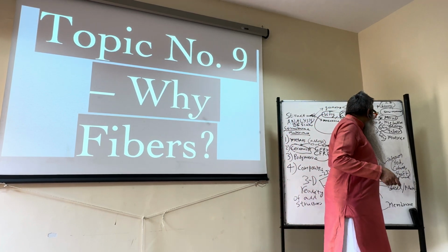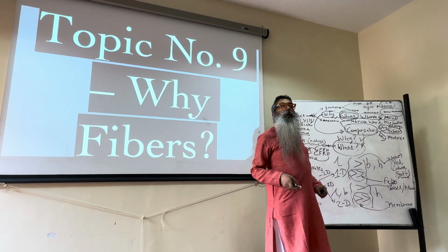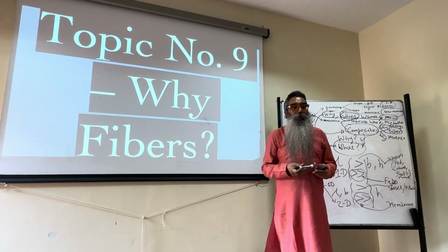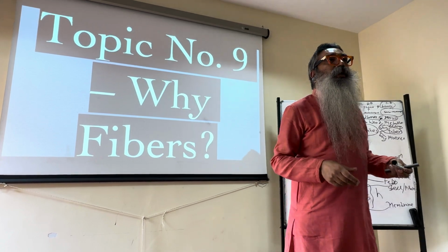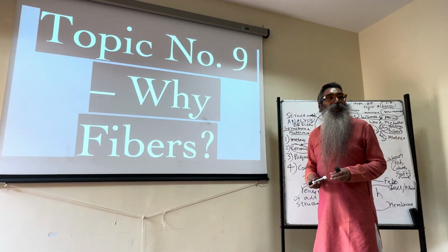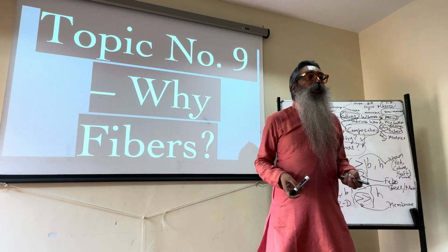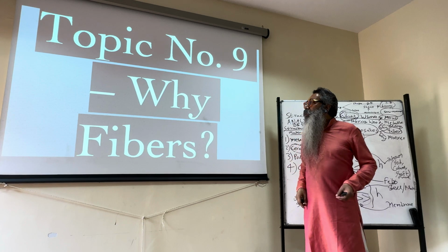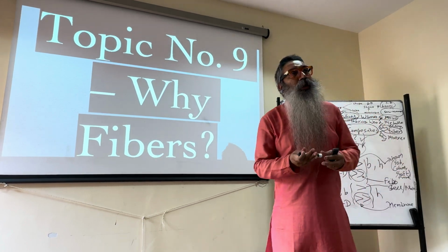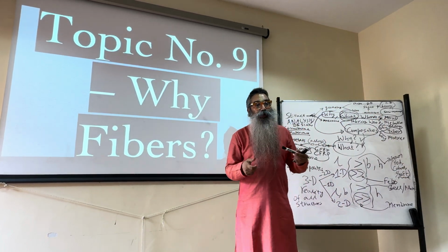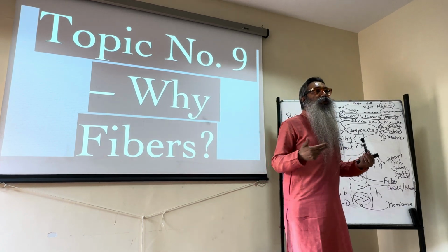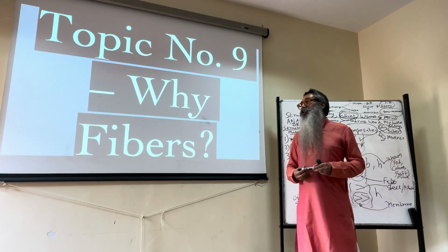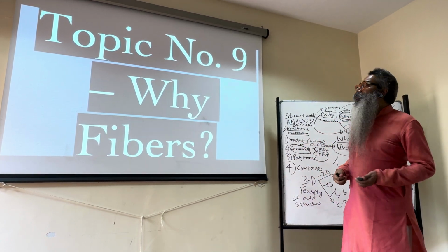And then we said very small, and therefore we can talk about it in the form of what we call the fiber, which has essentially the bending stiffness approaching zero. Okay, in the limit the bending stiffness is approaching zero. So it's all relative. It's not exactly zero. It's negligible compared to the other stiffnesses that are there, in particular compared to the axial stiffness. But of course they are in different units, so you must use an appropriate way to compare them by introducing a non-dimensional ratio of the two.